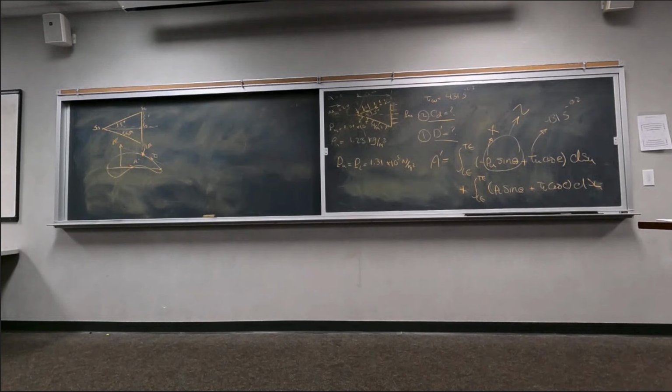So you understood the statement, right? What is the lift and drag compared to the flow direction? What is the axial and normal force? Okay. Then in this problem, since the angle of attack is 0, the flow direction and the chord direction are the same direction, right? Which means that lift is the same as your normal force, because they're going to lay on top of each other, and drag is going to be your axial force. So as soon as you calculate your axial force, you have your drag.